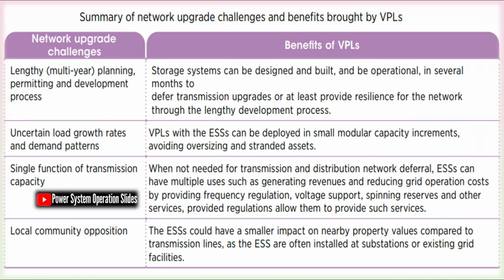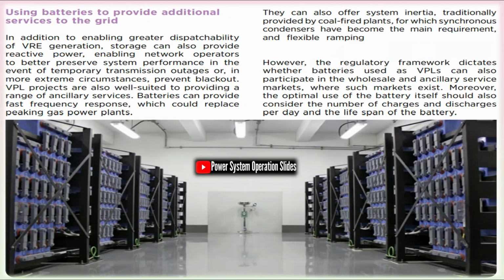Benefits. Avoids or defers costly transmission build-out. Using existing corridors and assets reduces permitting time and capital cost. Faster deployment: software upgrades and device installations are quicker than new tower or cable projects. Improved utilization: better use of existing lines through active control and DLR. Increased renewable integration: moves energy from high renewable zones without immediate new lines.